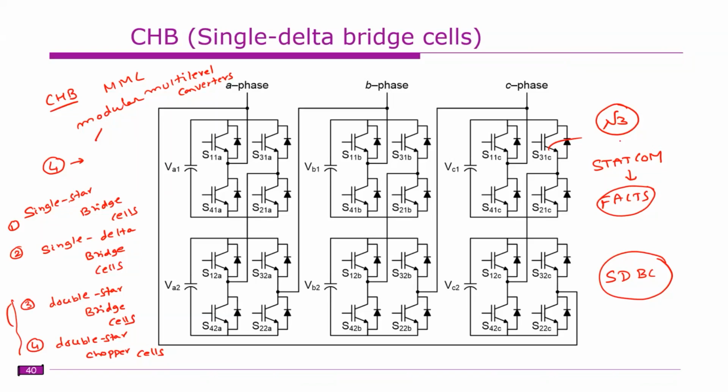So here the STATCOM is used in transmission lines, compensating the reactive power. In the case of this transformer, for example, if the load is an arc furnace load, you might study this in the power quality course, arc furnace loads will inject negative sequence harmonics or negative sequence reactive power.